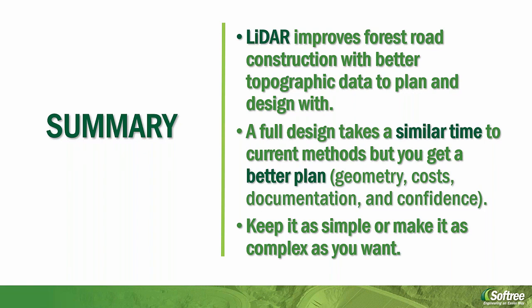Perfect. We do have a few questions coming in here, Matt. Our first question is, what is your suggestion for translating a LiDAR-based road design to the road crew on the ground who is actually building it? Well, that really depends on what tools you have available, and how closely you want things to match up. At the most basic level, if you're doing things ribbonless, you give them an alignment and get them to follow it as a line for the GPS.